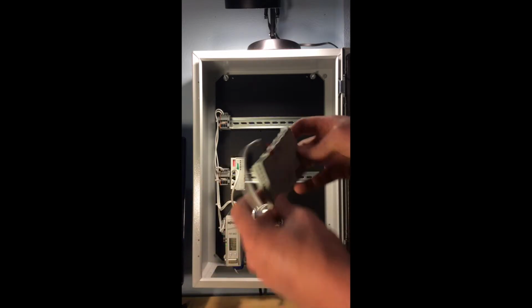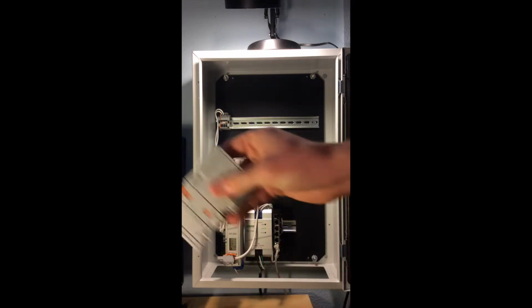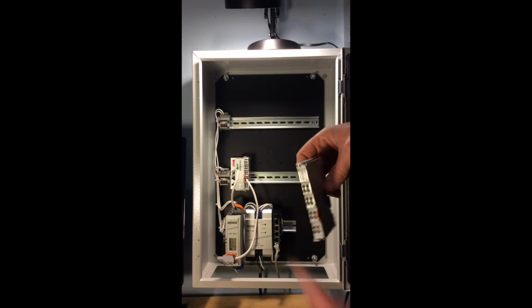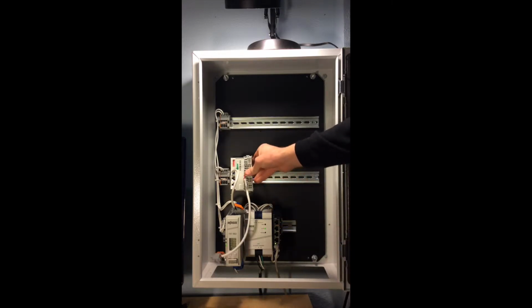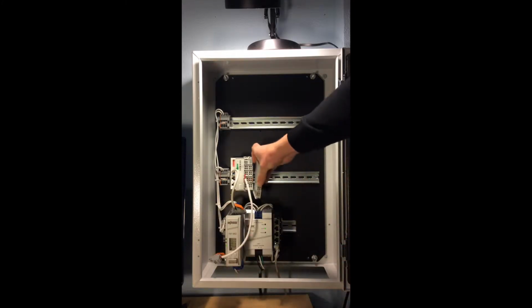We'll add a 750-602 24 volts DC power module to the system. Next we'll add our DC drive module. This is a 750-636 capable of 5 amps at 24 volts PWM control over the motor. And we'll close the node with a 750-600 end module.